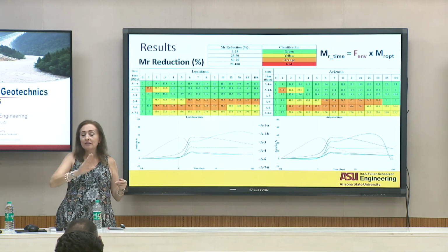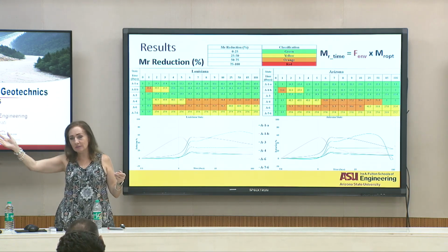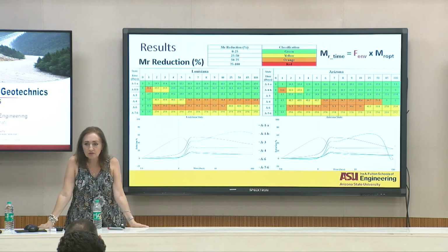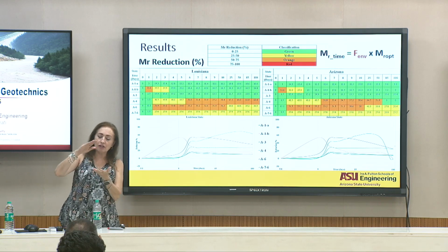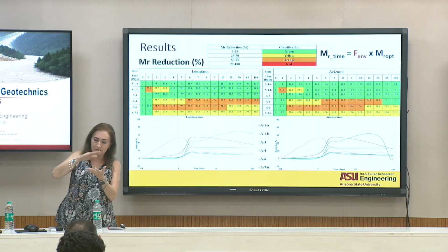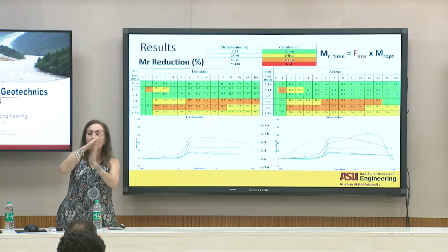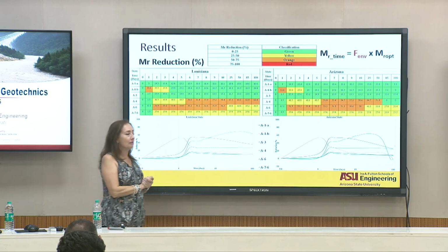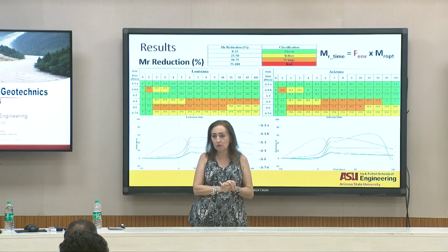And that becomes the elastoplastic behavior. But this one is the resilient modulus of the soil. You just get some repetitions that are creating some ruts, but not a total rut failure. These are repetitions that the pavement, the soil, will be able to withstand.